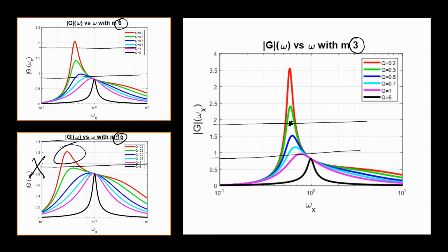This cannot be achieved here, and also you'll find that the curve here is falling very fast. When you change a very small value of frequency, you'll find that the gain is changing very fast, which is also not preferable. We'll go for a larger value for M, which is here, I think 6 or 6 point something. It will be a good option for M value. So this is 0.9 and 1.8. It can be something like this here. So we can operate at this range of frequencies.